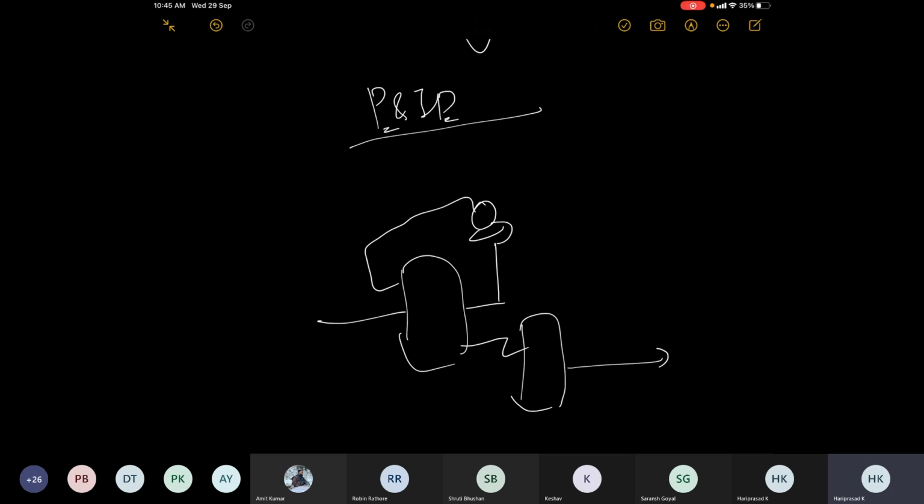You have feed in here, feed out. So this was the PFD. In the P&ID, you would show whether you need a valve here, because that is instrumentation. And how do you know the valve is needed? Then you need to know the level of the downstream tank. So the level will go, then there may be a level controller. The level controller would communicate to the control valve. So all the piping, this was not part of the PFD.